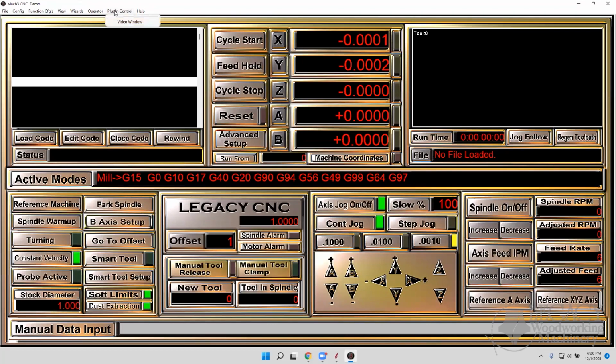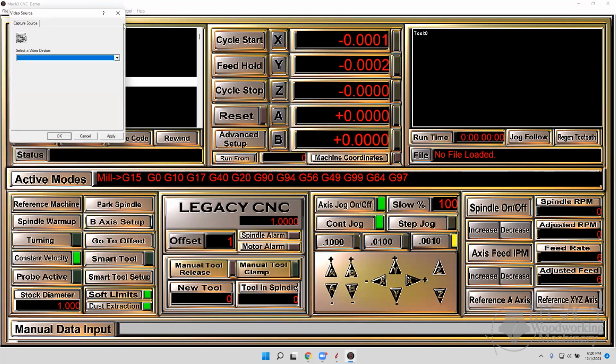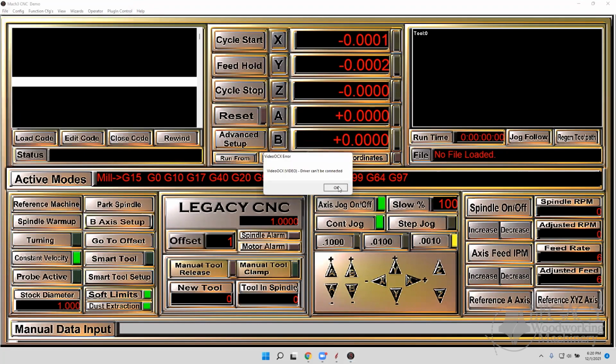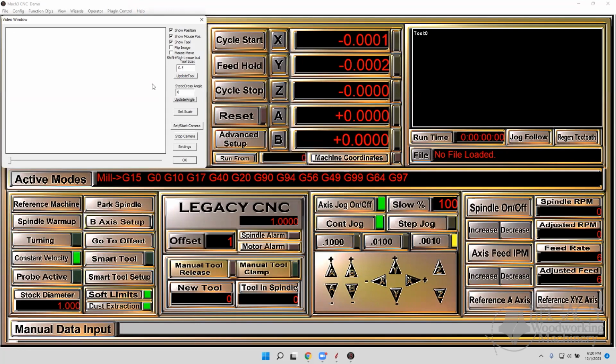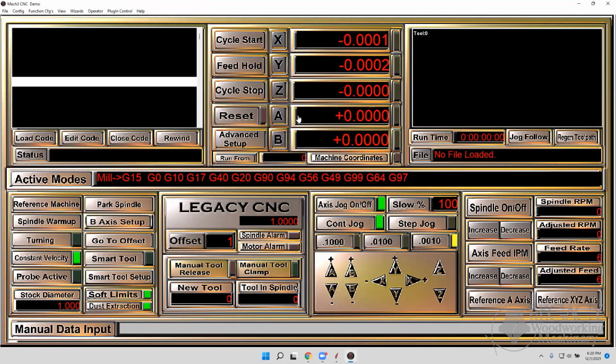If you go to plugin control, I don't have it here, but you would have the plugin that you have to have on your system to run, and it'll be in this list. When you open it up, it's going to have a setting that is a time delay. It's there so that you don't get erroneous noise on the system that flashes and tells you that it's touched. If that time delay is longer, it has to be in contact longer, so it applies more force. So we could go in and change that time delay to very, very short, and that might do it.